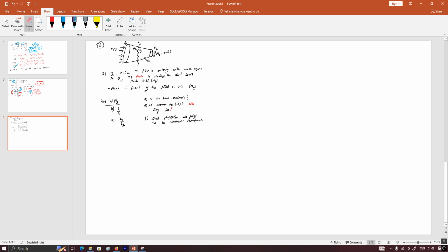And if it becomes subsonic midway, then for that subsonic nature, it will see it as a nozzle. So it will start to accelerate from that point. Okay, I think that is what is asked in this question as well. So let's see what is given. M1 is given, which is 3, and M2 is given, which is 0.85. So your flow exits with this Mach.